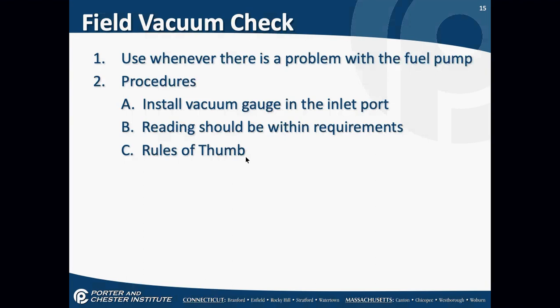So if I'm not pulling a 10-inch vacuum on a single-stage pump when I'm just testing the pump, what am I going to do? Do you replace the pump? Yeah, just replace the pump. Okay? Now,